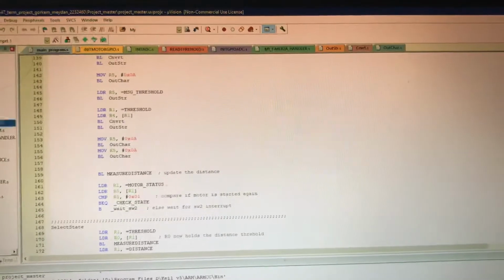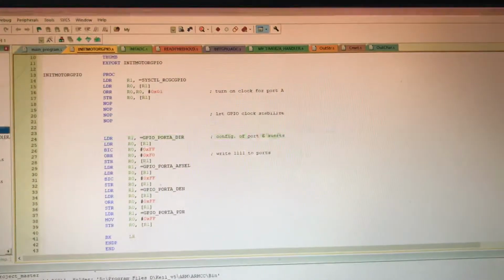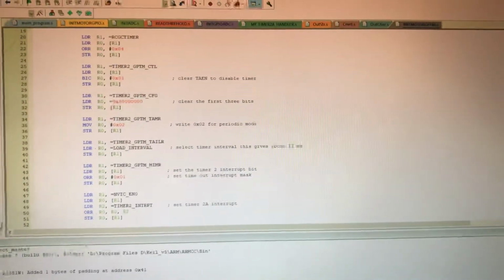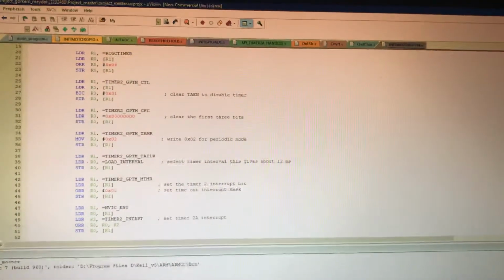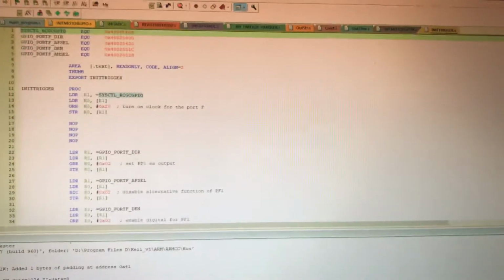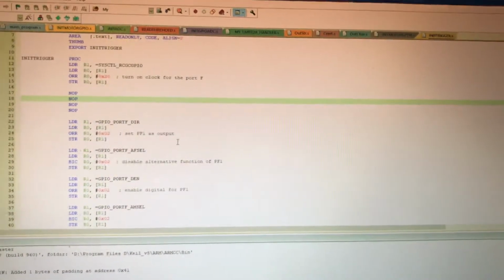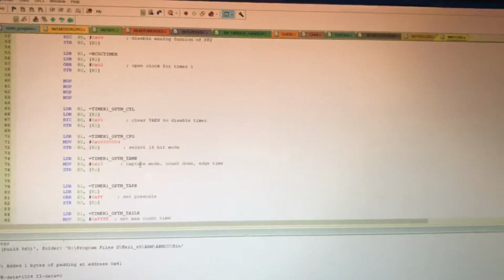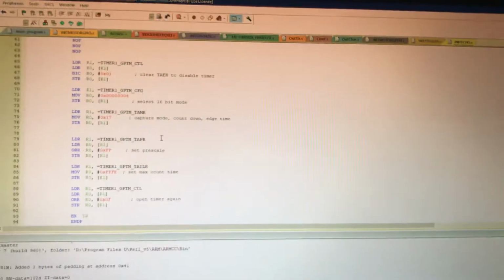I have motor GPIO setup code, a GPTM timer initialization mode to run the motor at the GPTM timer interrupts, and its handler that gives input to the motors. For the distance sensor, I have initialization code for the trigger that initializes it as a regular output port, and initialization for the echo port that initializes it as a GPTM capture mode at edge time that counts both edges.